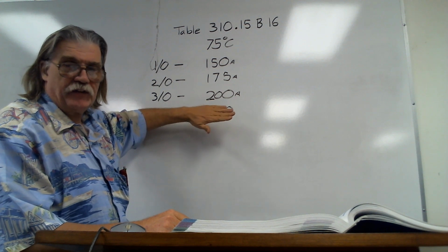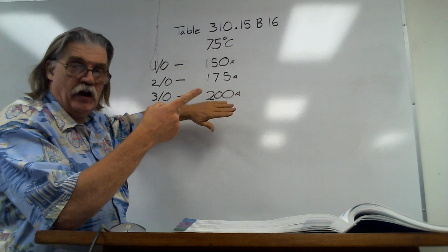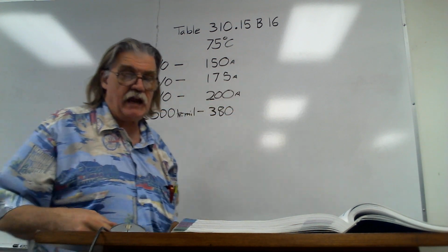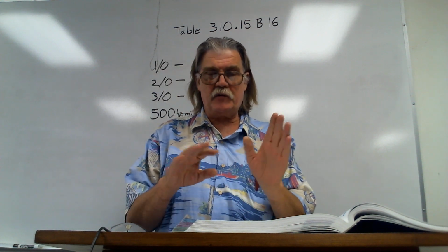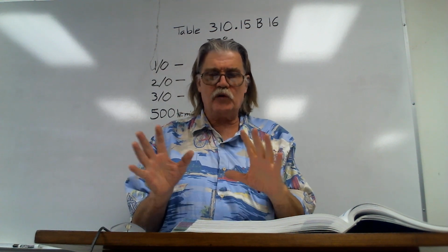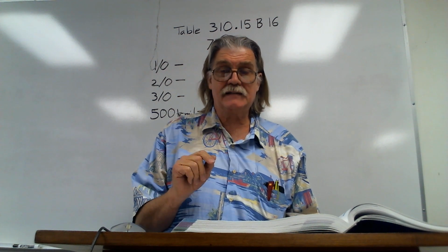Now we'll talk about the 500 kcmil in just a second, but let's go ahead and look up those standard ratings real quick. Remember I said we're going to look at the standard ratings, and how do we know what the standard ratings are? Article 240.6.